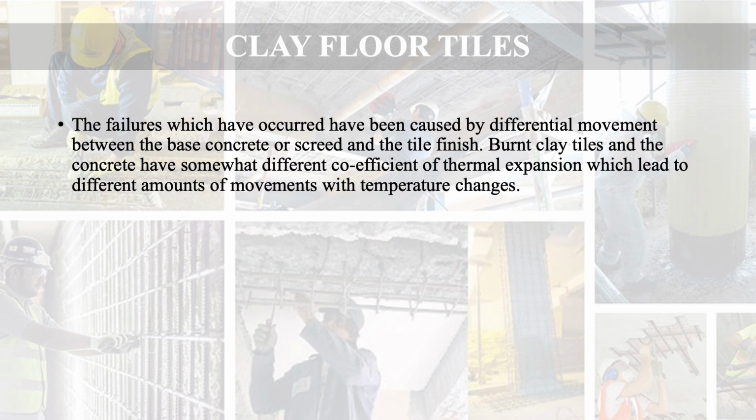Failure in this type of flooring may be caused by differential movement between the base concrete or screed and the tile finish. Burnt clay tiles and concrete have somewhat different coefficients of thermal expansion.